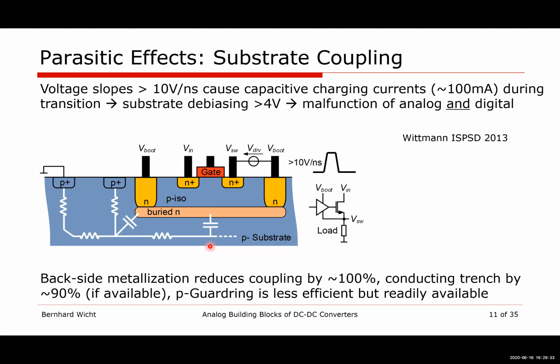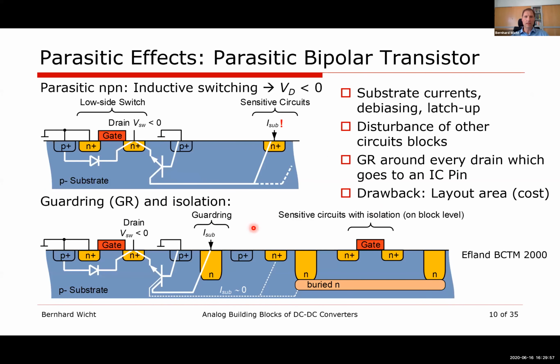Okay. Thanks. Okay, I'm sorry. May I have one stupid question? In your experience, SOI technology and the bulk technology, which one is better? Right now, if it's high voltage, I'm really excited about SOI. It's a simple answer. If you look at these parasitic bipolar effects, they're really nasty. In my career, I had to deal with so many bipolar effects and get them solved, that I'm so happy that we have SOI nowadays, where everything simply disappears.